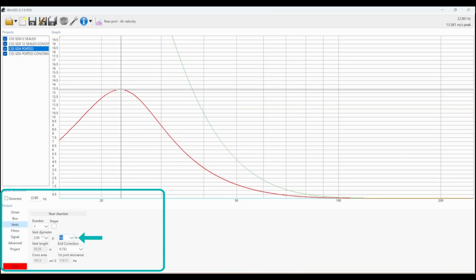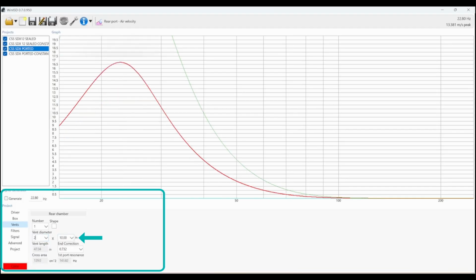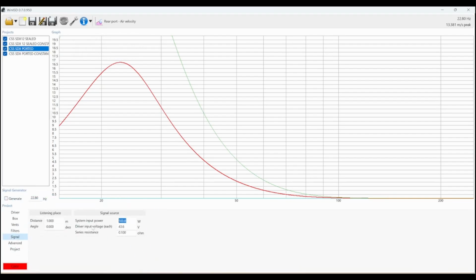So we will nudge these numbers in our favor, and what we can do is just make small changes. There we are. A 2 by 10 inch vent on this particular subwoofer at the half power mark, which is a nice safe mark for sound quality reasons, has, in my opinion, below audible threshold vent noise that could annoy you in use. This number here is great.